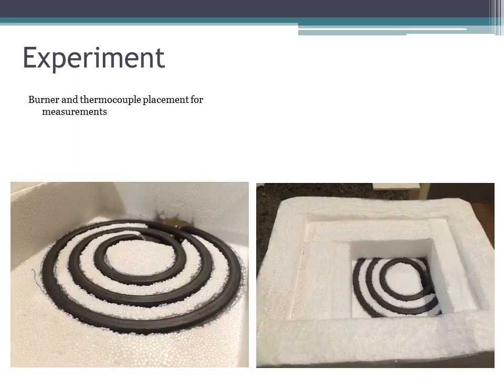We also let everything rise to a steady state, and we were redundant in checking that there were no cold or hot spots. Then we put a thermocouple above, trying to get it as close as we could to being above the other thermocouple, and we used LabVIEW to display the data and verify when we did reach a steady state.